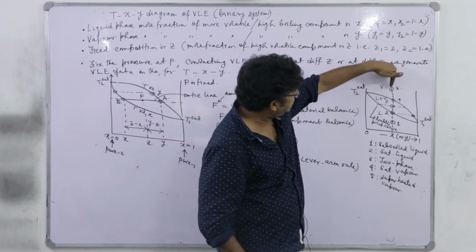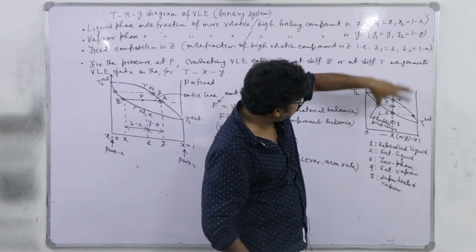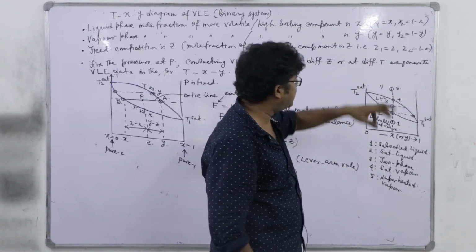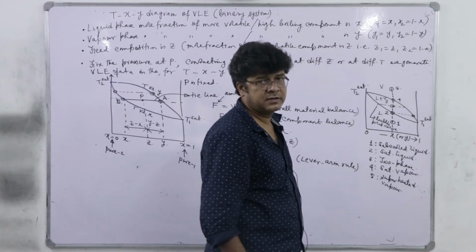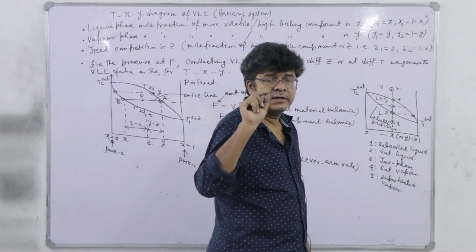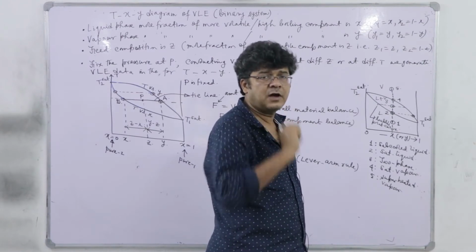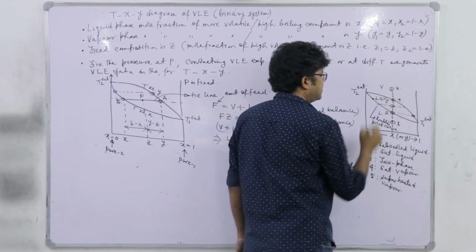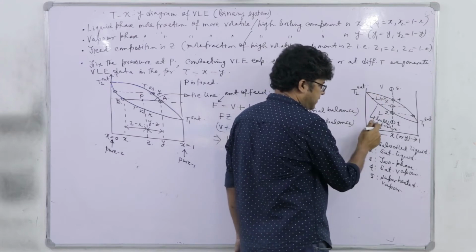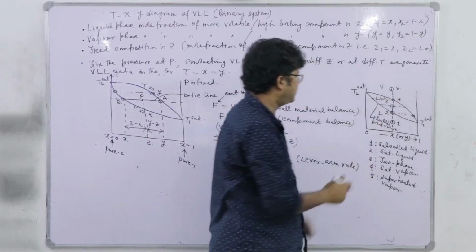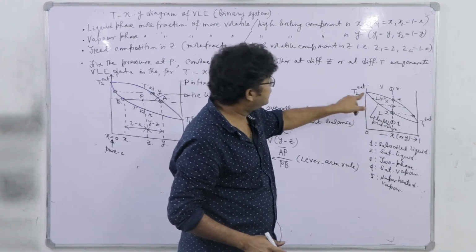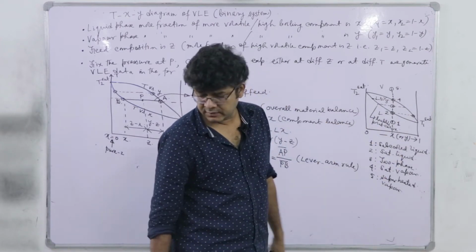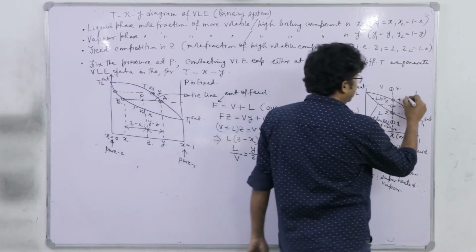Now, similar to bubble point, let's think of this changing of thermal state in the reverse direction. Let's say I have a superheated vapor and I go on reducing its temperature. So there will be a point where the vapor is just saturated and the first drop of dew will appear, right? So the dew will have a composition here, because this is the vapor phase, this is the liquid phase, the dew is getting formed and it has a composition same as this point. So similar to the bubble point curve, this T versus Y plot is alternatively referred to as the dew point curve.